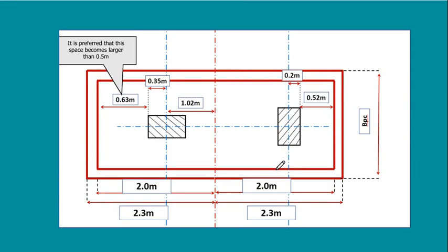Let's see this in a plan. Yes, this is a bigger plan. This is my new plan. I calculated the length from here to there, multiplied it by 2 to get the full length, and once I get the full length and put it on my plan, I have to check this cantilever. I assume this cantilever to be 0.52 meters. The other cantilever should be more or less equal. Suppose that I assume this to be 0.52 and then I check here and I found that this is 1.00, here my design is not optimum.